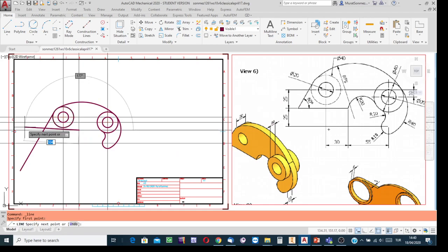Similarly, I created that tangent line longer than its magnitude. I'm going to do the same thing. Since I don't know the length of the line, I'm going to create it with further extension, for instance, as if the length of the line were 110 or more. Click the tab key. Why the tab key? Because you see within the other box I have the degree symbol and arc simulation exists. Click the tab key and into the box write the angle 180, the inclination angle relative to the dotted horizontal line. Press escape.